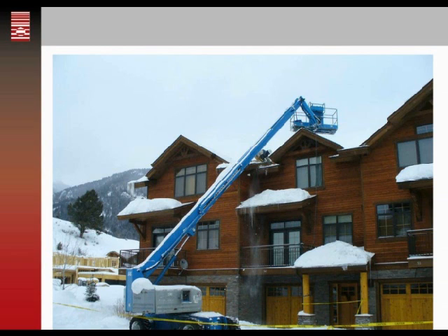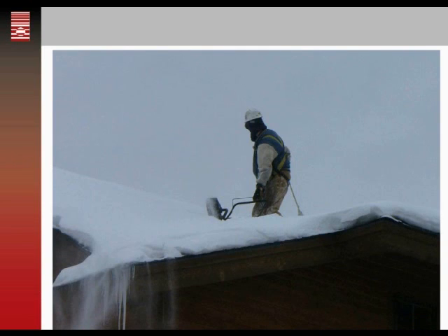This was, as I recall, about a 40-unit condominium complex, and about 2/3 to 3/4 of them had water leaking in from these ice dam issues. So certainly huge problems. It's in areas of high snow levels and in cold temperatures. These were below zero temperatures when we went out and did this investigation. So the first step was knock all of the icicles off of the roof to prevent people from getting injured, and then snow blow off the snow. So now the water can't leak in if there's no snow on the roof.